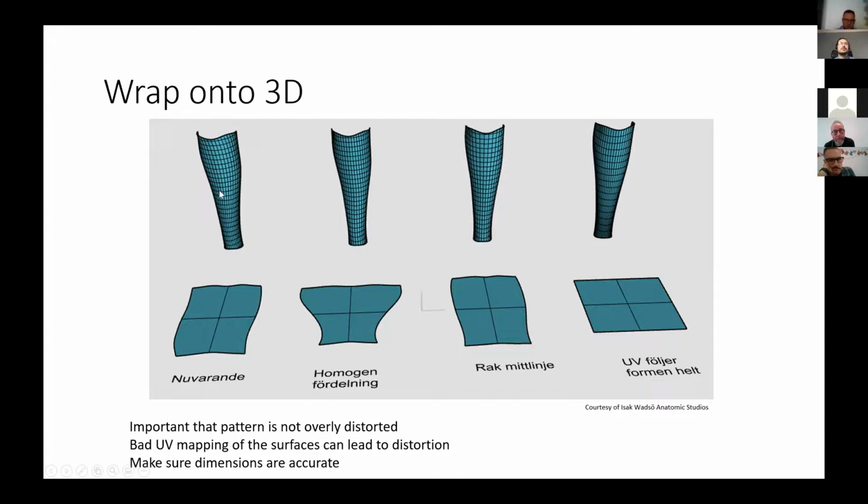It's a doubly curved surface, so there isn't any way to do this perfectly to wrap this onto a flat sheet. It's just like trying to get sections of a globe, for instance. There isn't any mathematically possible perfect way to do this, but there are, of course, better or worse ways of doing this projection. So for instance, the default way of doing this in the software generates, as you can see on these pictures here, a fairly wobbly and non-uniform scaling of these